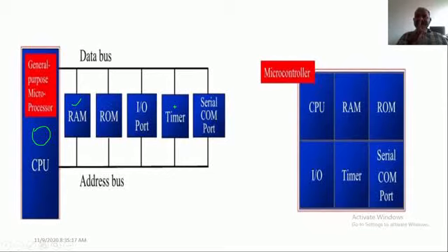When I would like to interface the input device with the microprocessor, if it is not working with the same speed as the microprocessor, then I should introduce some delay cycles to the microprocessor. That may be done with the help of the timer. The same timer can be used to generate the time delay in terms of seconds for the external devices. And also the same timer may be used as a counter, which is a different scenario. I'll explain this later.